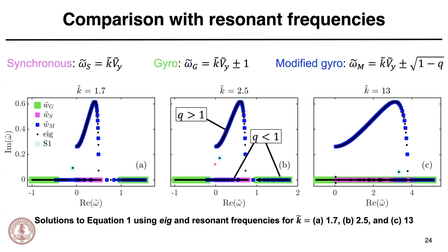So that's how come it was not able to get them. But now the question remains: this Q greater than 1 branch, does it really mean anything? And just to put a little bit more into context, in usual studies of magnetrons and crossed-field diode flows, the profiles usually have Q equal to 1 or Q less than 1, where Q equal to 1 is called a Brillouin flow. And this is just due to observations in the device that either Q equal to 1 or Q less than 1 is often desired, or just what is observed.